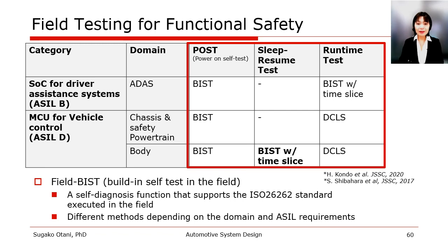Field-based, a self-diagnose function, is executed in the field after manufacturing test. To test an automotive LSI, the field-based test is required to meet several constraints, including the specified metric and the limited test application time. Field-based can diagnose the safety mechanisms to achieve the required latent fault metric.